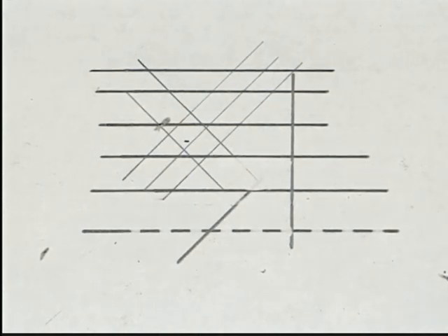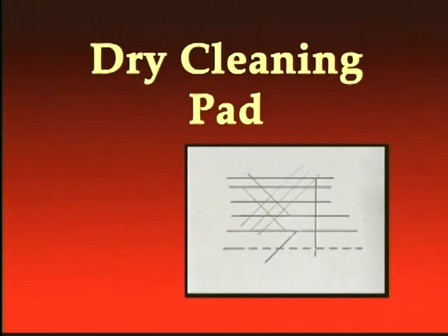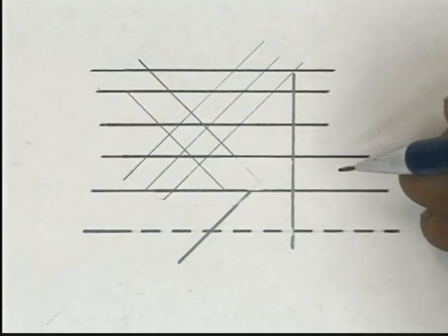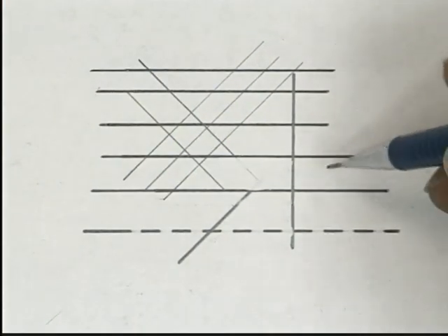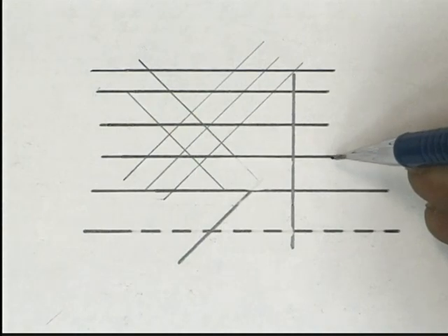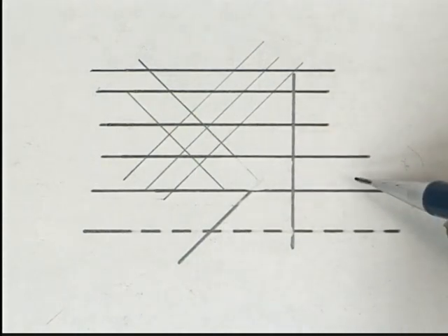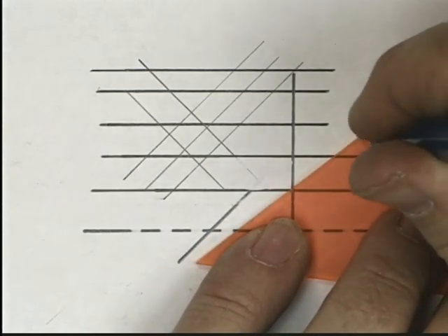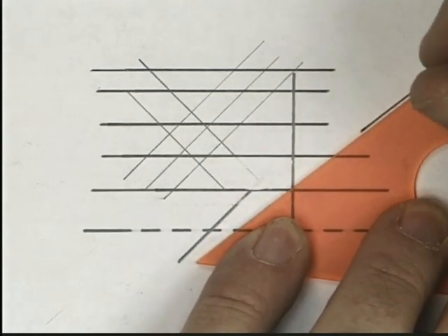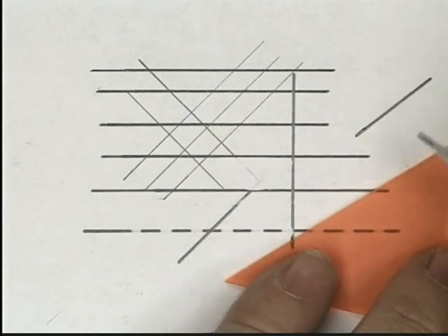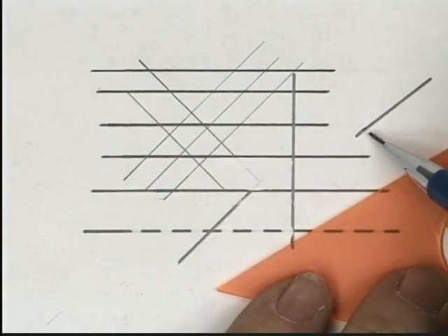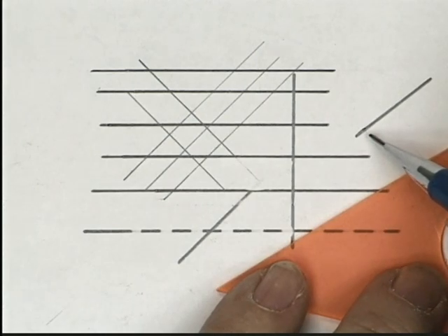One of the things you'll find that happens when you're using especially the 2H or the HB lead that's a little bit softer, and by the way, remember you need the softer or the medium soft lead to make these nice dark object lines. But what will happen when you draw with this and you press really hard, now I don't think the video camera is going to be close enough to show you this, but if we looked really, really close there, you would see some tiny, tiny little granules of carbon that broke off the edge of the lead.